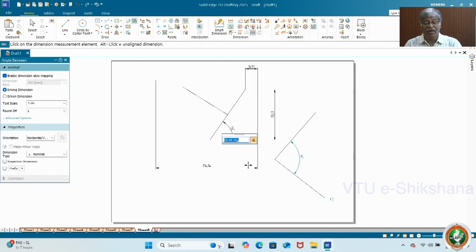See, there are options. You have drawn some line with some random value or 56 intentionally. Now, if you would like to change that to some value, say, instead of 56, I am interested in 50. Yes, you can just say yes. So you will get the 50-degree fixed. You have a lot of options here. Okay, you can always use them.